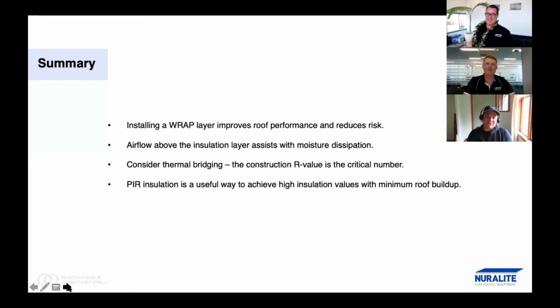Yep, in the new and old H1, there's effectively three methods you can use to prove that you have sufficient insulation in your building. The first one is the schedule method. You just show that the R-values for your walls and your roof and your windows and your floor are above a certain number. And you can do that by just referencing the BRANZ Home Insulation Guide, which is what most commonly everyone does, or using Design Navigator online, or using a more complicated tool like Passive House Planning Package or BEACON, right? That's the schedule method. So it's kind of the simplest one.